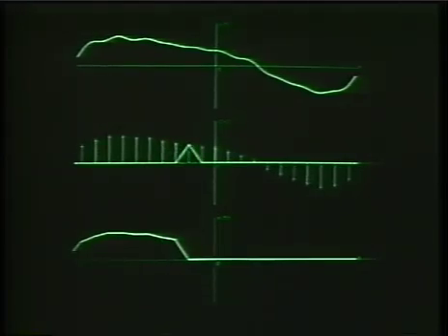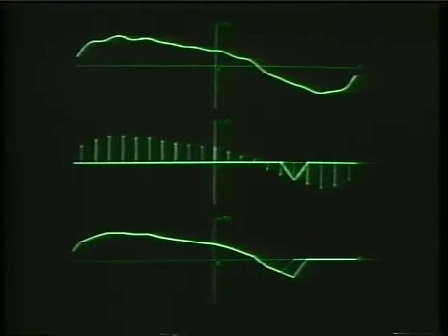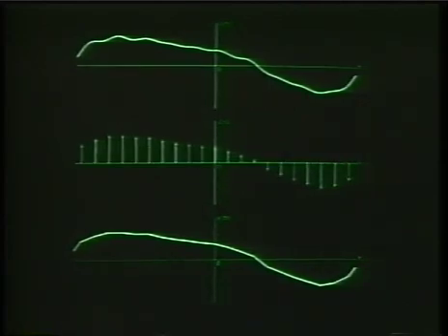Then we'll speed up the process, and as we proceed through, we are building basically a linear interpolation in between the sample points, essentially corresponding to, if one wants to think of it this way, connecting the dots. And what you're watching once again is essentially the convolution process, convolving the impulse train with the impulse response of the interpolating filter. And what we're generating then is a linear approximation to the band-limited continuous time curve at the top.